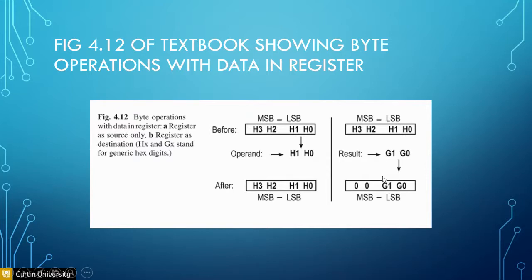Again, I just like to repeat so that you get what I mean. move.b R5 R6. Only the lower byte is affected, just like what is happening here. The higher byte is not affected. So if the original R6 does not have any value initially, it will be 0, just like what we have here.